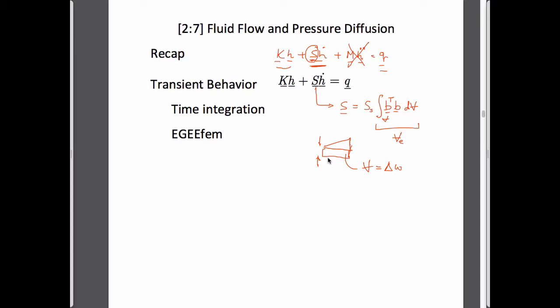They merely allow us to say that if there's a change in the nodal condition of head, how much fluid gets squeezed out from that tributary area. If it's a consistent matrix, it comes from both nodes, both ends of the element. If it's a lumped matrix, it comes only from the node where the dependent variable changes. Head changes at node 1, then fluid comes out as a flux in a time step at that node. And that's the physical meaning of it.